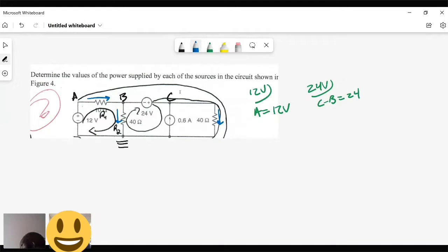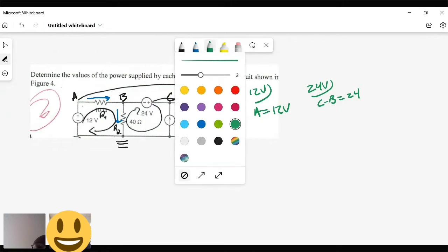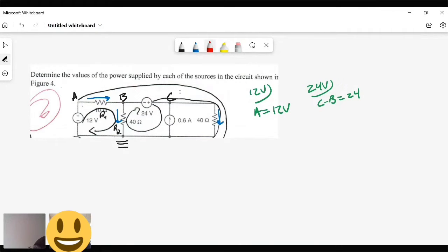Last step is what? What do you have to do now? So would we want to find the voltage? Will we use that 10 ohm resistor to find the voltage of B? Node B or supernode? Because it's not solved. This one's solved. A is 12. If you have a voltage source and it doesn't solve, it gives you an equation, automatic supernode.